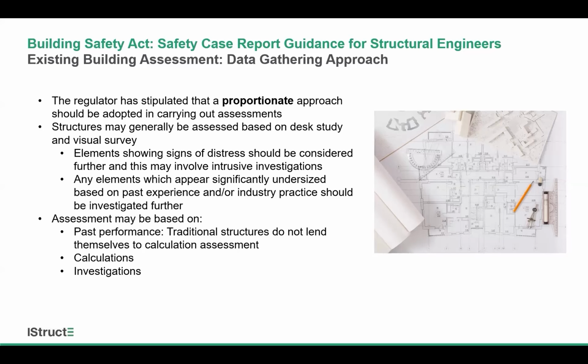The assessment itself, the approach can vary depending on the nature of the building. So it could be based on past performance, particularly if they're quite old buildings that predate more modern design codes. They wouldn't necessarily lend themselves to a more traditional calculation approach. So it might be a degree of looking at past performance in similar buildings and generally the condition of them. It could feasibly be based on calculations or spot checks and review, scheme design guidance, etc. And also to some degree on investigations and further review. But I'll talk about all of that in subsequent slides.